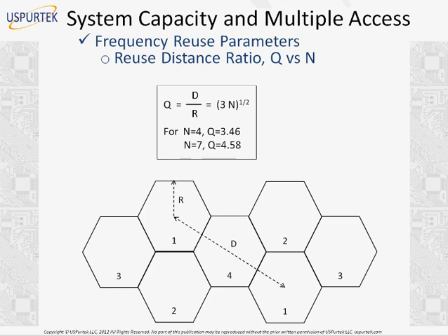So if n is very large, of course, the benefit I have is that the two cell sites will be far apart. There will be almost no co-channel interference, because the two cell sites are so far apart when the frequency repeats. But the downside is that I have reduced the bandwidth that is available in one cell site. I have only 1/10 of the bandwidth now. If I had used n equals 4, then I would have 25 megahertz, so I could have served more users in my cell site. So it's really a trade-off between capacity and quality.